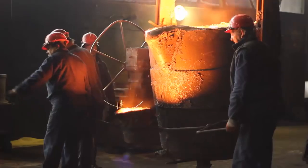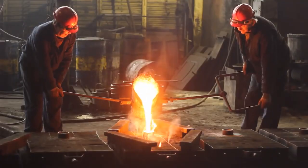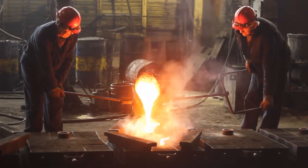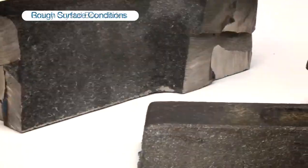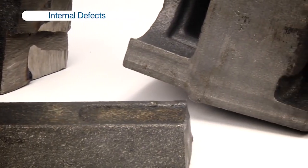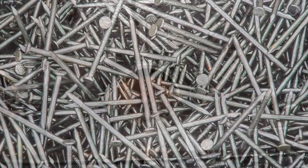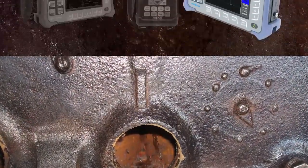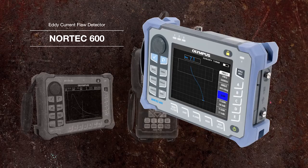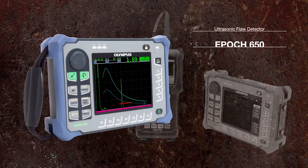Cast components are manufactured by pouring molten hot metal into a sand mold. The molten metal is then cooled and solidified, forming the part. As a result of the manufacturing processes, castings generally end up with rough surface conditions, grainy crystal boundaries, and have the potential for internal defects. Due to these characteristics, there are a number of non-destructive testing techniques that apply to cast components. These include eddy current tests for surface cracks, an ultrasonic test for thickness, porosity and voids, and graphite nodularity.